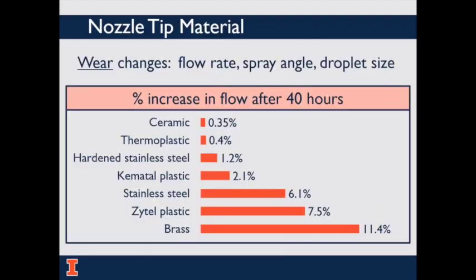When selecting a nozzle, the orifice or tip material is worthy of note. Nozzles are a high wear item, and the rate of wear depends on factors such as the nozzle tip material, spray formulation, and operating pressure. Looking specifically at the impact of nozzle tip material, consider the chart here, which shows the results of a 40-hour wear test on nozzles of various materials. In this test, wear was defined as the percent change in flow rate for a set pressure.